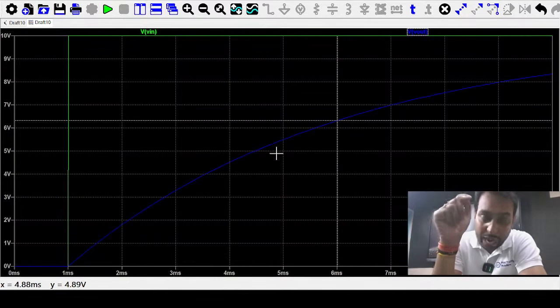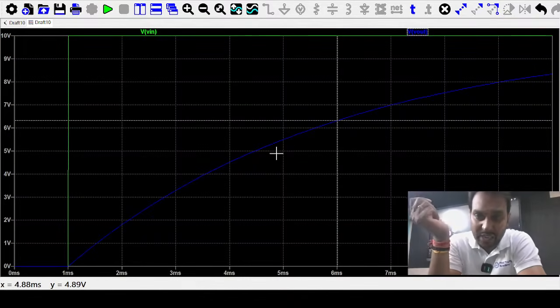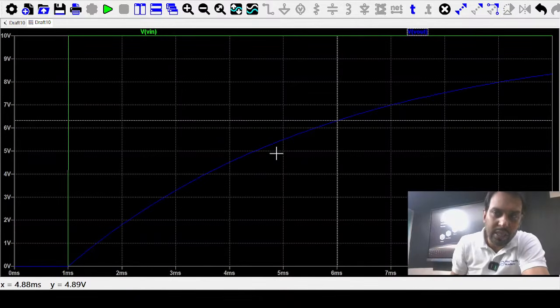You can convert your non-linear graph into a linear one with the help of a different circuit. We will discuss in the next class how you can make the capacitor charge linearly. Whenever you have a resistor and capacitor and a voltage, the capacitor always charges exponentially, but with the help of current we can charge the capacitor linearly. As time goes on, the capacitor is charging, and from this we can understand that the charging depends on the tau value.